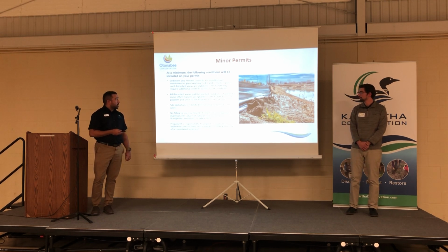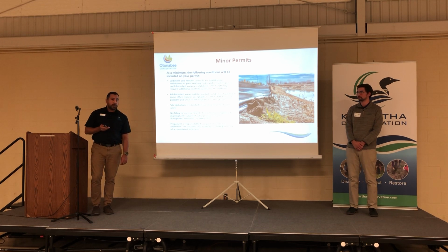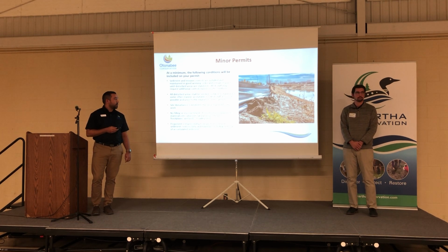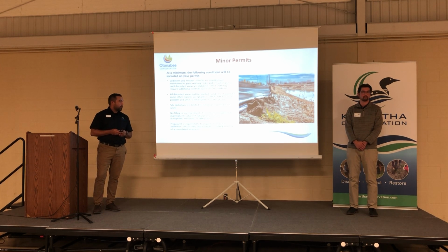Again, disturbed areas are seeded, sodded, or stabilized in another manner that's acceptable to Orca staff. And that has to be done as soon as possible, but at the very least before the permit expires. And site disturbance should be limited to the area required for the work. No filling or encroachment of construction equipment or materials into adjacent natural areas, streams, floodplains, wetlands, or valley lands, or